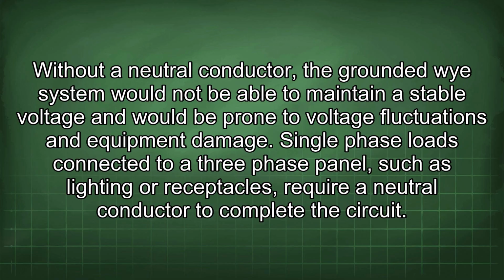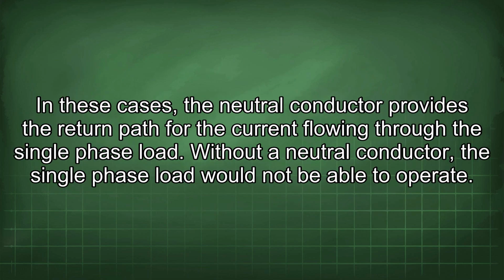Single-phase loads connected to a three-phase panel, such as lighting or receptacles, require a neutral conductor to complete the circuit. In these cases, the neutral conductor provides the return path for the current flowing through the single-phase load. Without a neutral conductor, the single-phase load would not be able to operate.